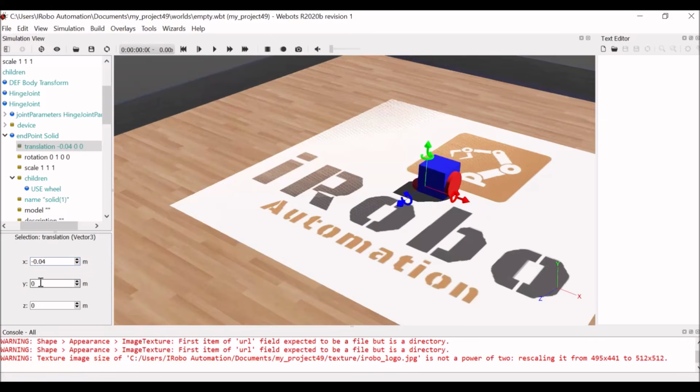Okay, the rotation means the second wheel is flat, it is on the floor, horizontally. I want it vertically, so make y 0, make z 1, and we have to rotate 90 degrees, so 1.57.